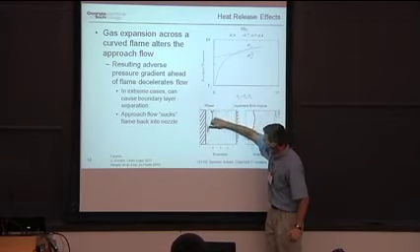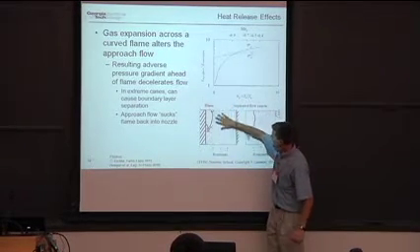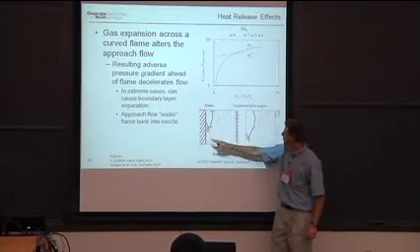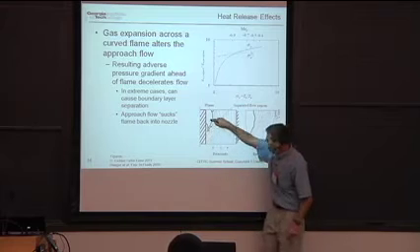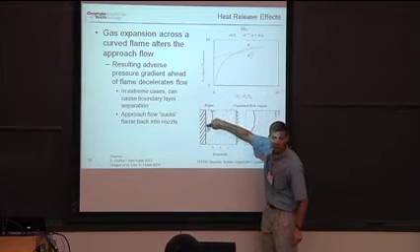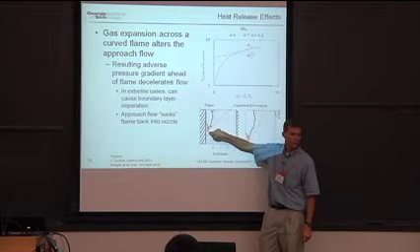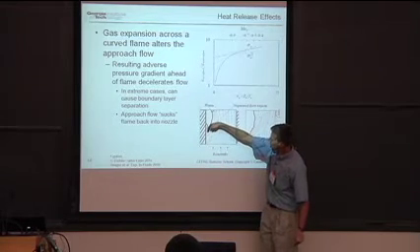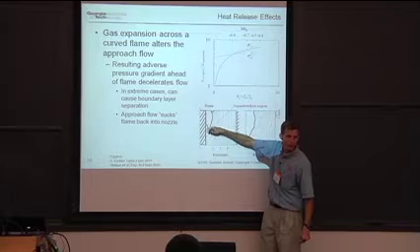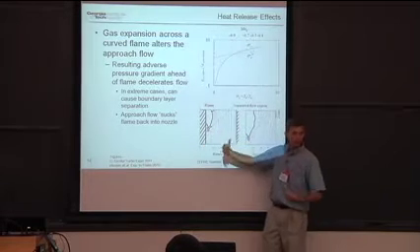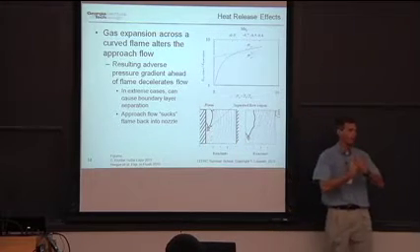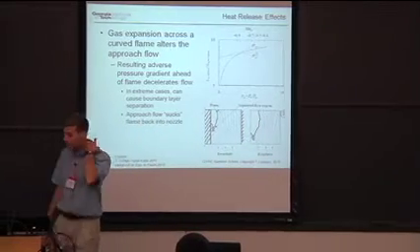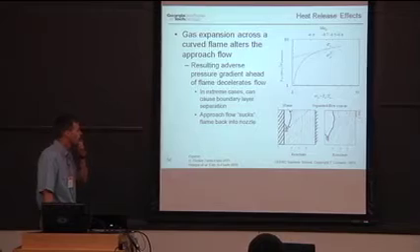So this is an image of the instantaneous flame. These are streamlines of the flow. And what I've done is I've hatched out the separated flow region. So look at that. Right in that positively curved region, the flame is causing reverse flow. It's actually causing boundary layer separation. So what happens? Well, the flow is going backwards, so the flame shoots upstream, which causes the boundary layer to separate, so the flame moves upstream. And so the flow is actually sucking the flame back up into it. You totally have to include heat release and gas expansion effects in order to understand this problem.